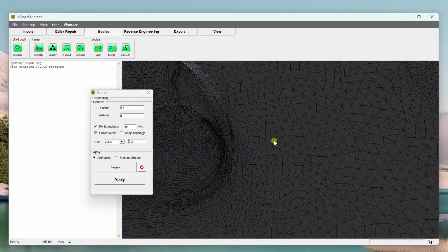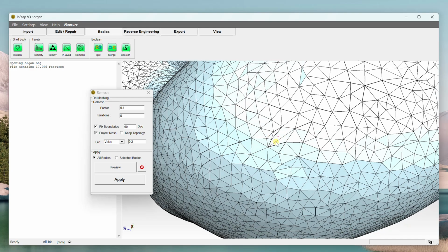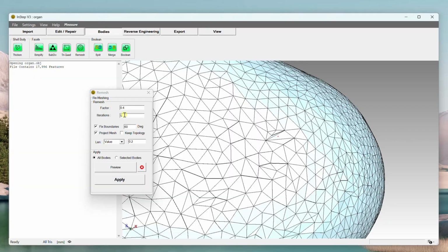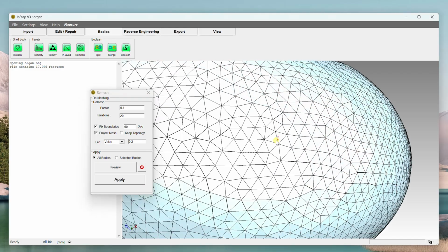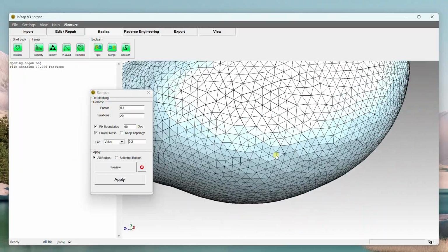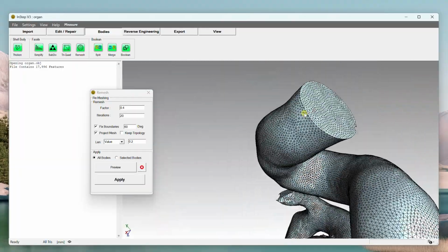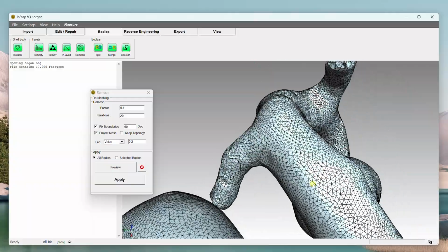We have a few places like here where you can tell that the edge is probably going to cause issues. So we're going to set our rotate marker there, and we're going to increase this to say 20 iterations. Now you see with more iterations that gets refined better and better, and we end up with a mesh that's actually very uniform in scale and look and feel.